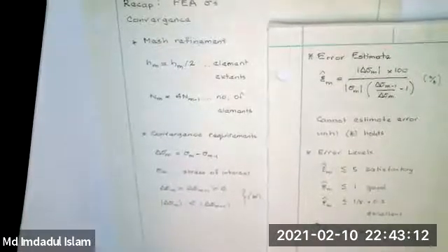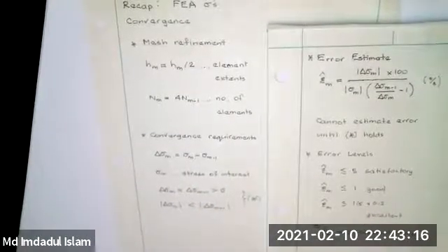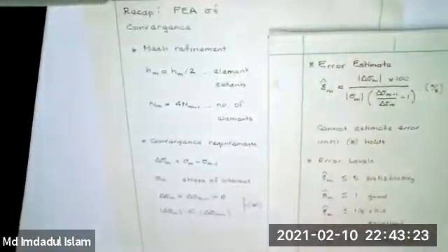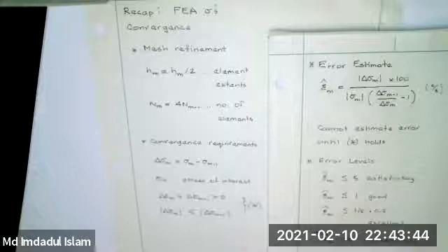There are some crude designs. Some of the stuff I've seen in the oil and gas industry is seriously over-designed, and that's because that makes it safer, and the costs of being over-designed are insignificant. When you have moving equipment like automobiles and jet engines and planes, when you add extra weight, then you're going to add extra cost to the operating. The extra cost of putting some extra steel in a pipeline is not that big a deal.